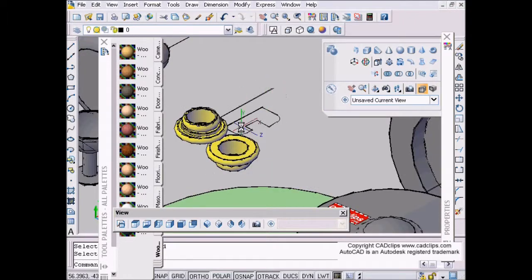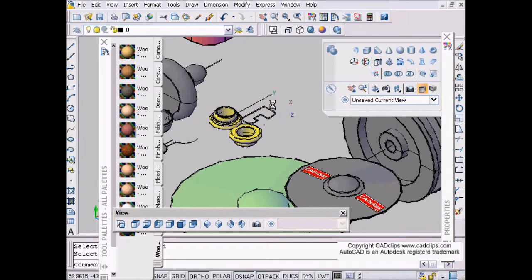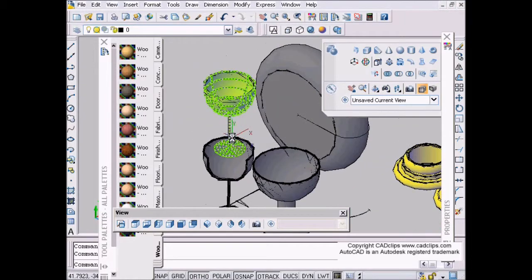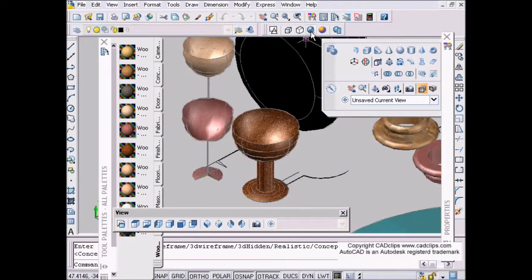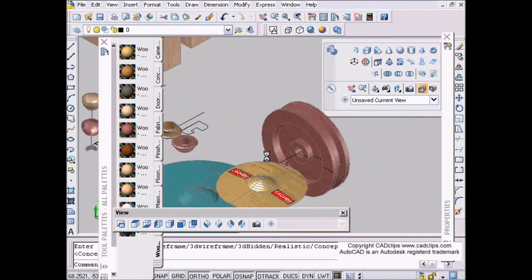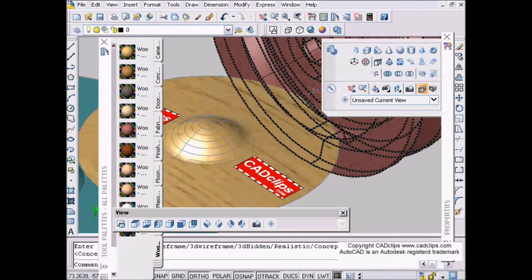Okay, some different examples here. Depends on the axis. The main thing is your axis has to be on the same plane and the object has to be able to revolve around it, and then it can't interfere with itself as it revolves around, and then from there it's a matter of adding in your materials and some stuff that we're going to talk about in some future lessons.